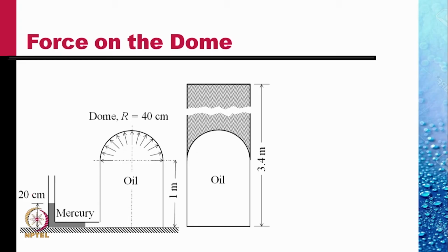Clearly then, the vertical force on the hemispherical cap is equal to the weight of oil over and above the dome, shown as gray in this picture.